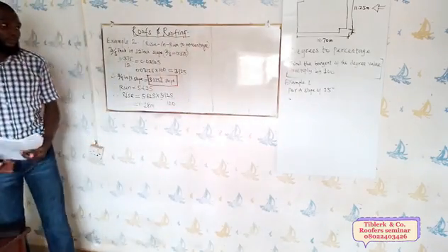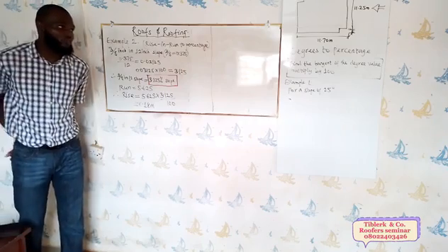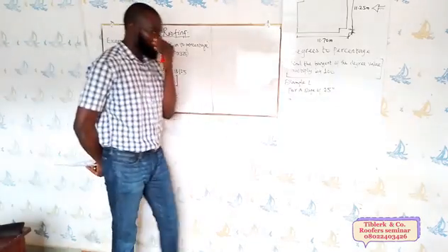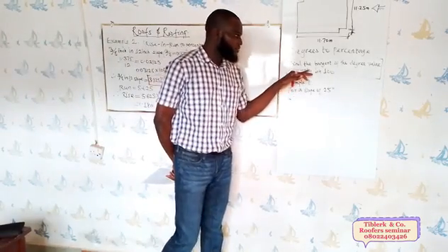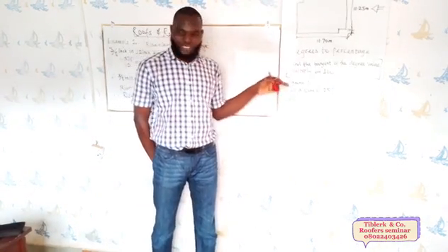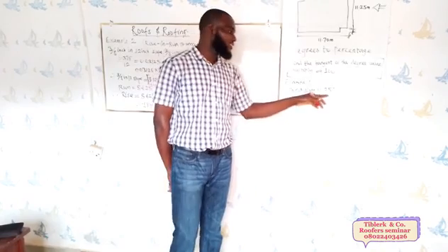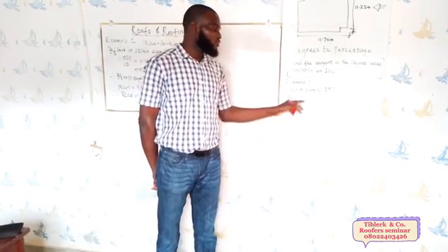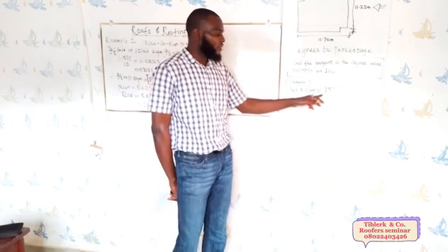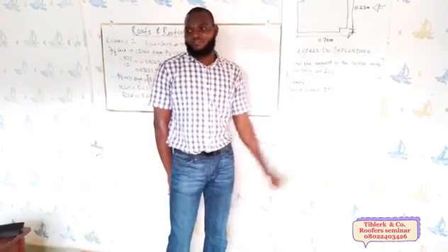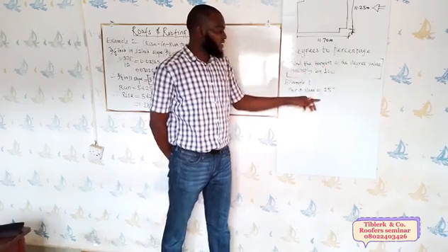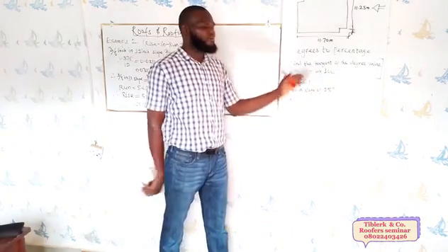You see, for us to convert from degrees to percentage, all we need to do is to determine the tangent of the degree. So that the specification is now in degrees. So we have been asked to find the percentage for a 25 degree slope. So the solution is to find the tangent of the degree, times 100.